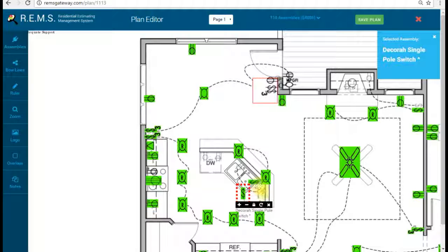Another good example here. Chances are there's not going to be a 2 gang pushed underneath that ledge. So when I do my plates, I will do it as 1 gangs, where obviously these are going to be turned to the side underneath this ledge. But for right now, we're just trying to show that we counted the switches.